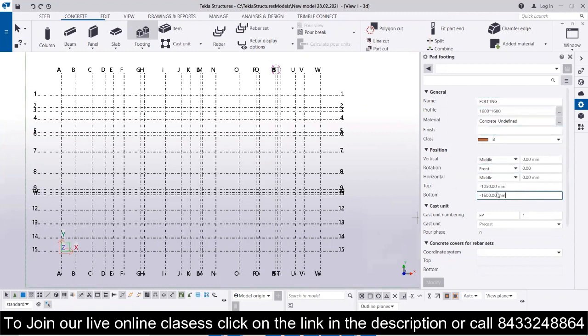Now we have to place the footing at the proper place. And how you can get that? You will have to match the intersection point of the grid lines in the Tekla structure and the intersection point of the grid center lines in the AutoCAD drawing. Okay, so we will start with it.